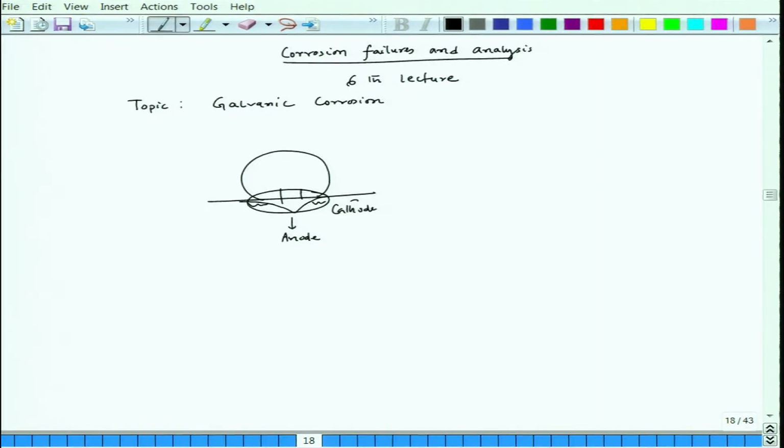And we related this phenomenon with uniform corrosion, saying that the droplet also forms sometimes here, sometimes here, sometimes here. Finally, those localized corrosions are connected together and give a uniform mode. So, this segment is uniformly corroding, but if you look at one particular droplet, it is localized.